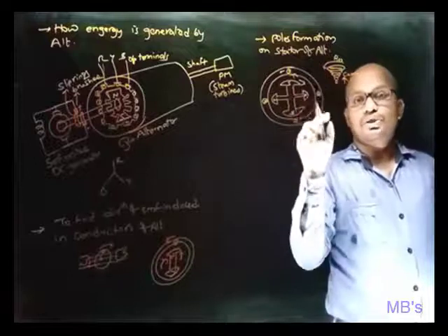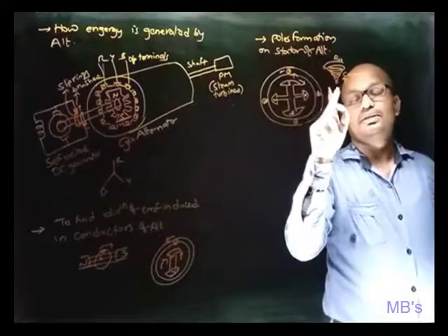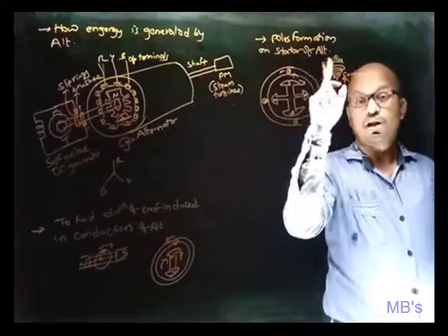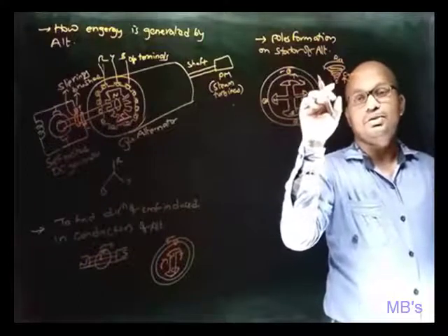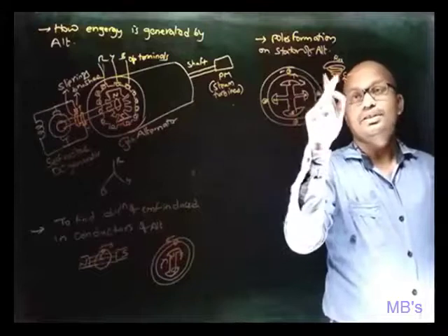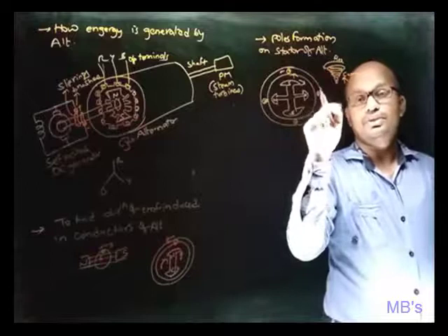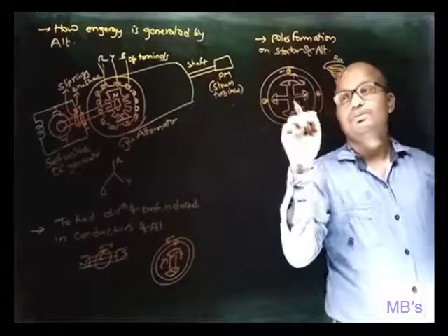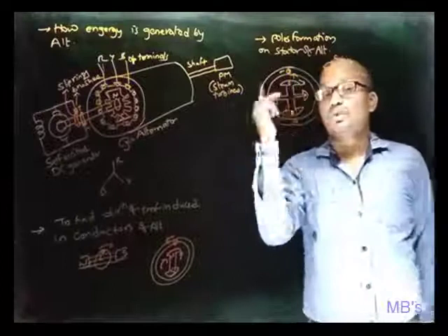So if the direction of rotation of the head is anti-clockwise, then the direction of advancement of the tip is outwards. Meaning if the flux direction is anti-clockwise, then the current will be outwards. If the flux direction is clockwise, then the advancement of the tip will be down, meaning current direction will be down. So here the direction of current we took is outwards.